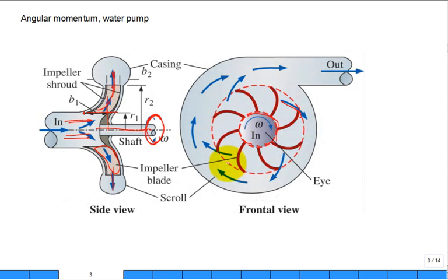Okay. There's some dimensions that are important. What is R1? The radius of the inlet. Yes, the I region, and the R2, the radius of the outer impeller. What is this B1? That's complicated. What is B1? It's the height of the water passage in the I region. Does that make sense? And then what is the B2?